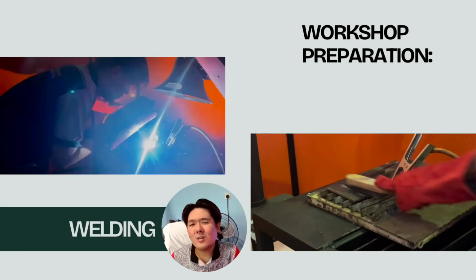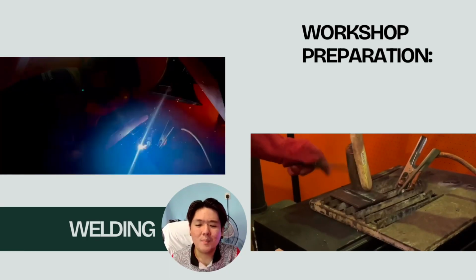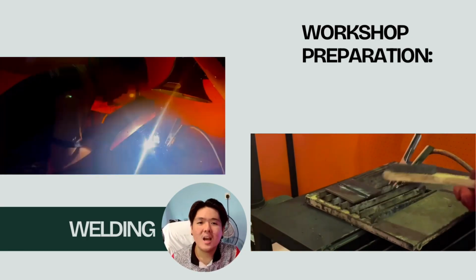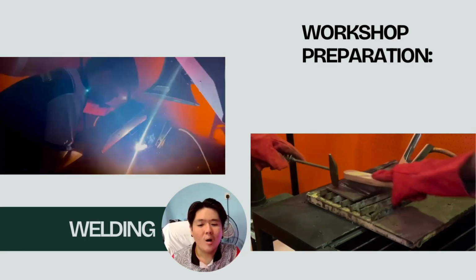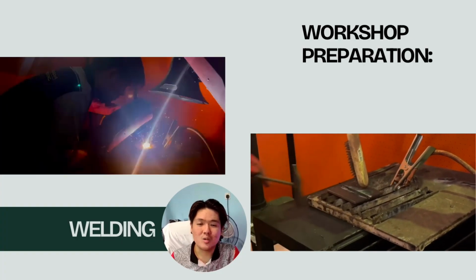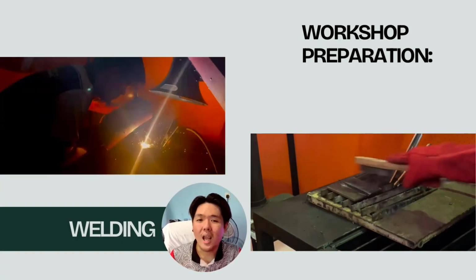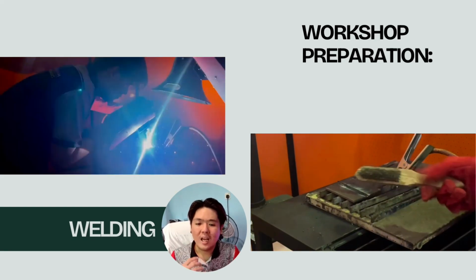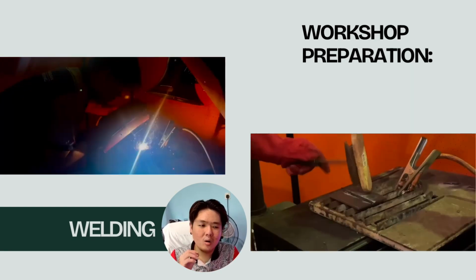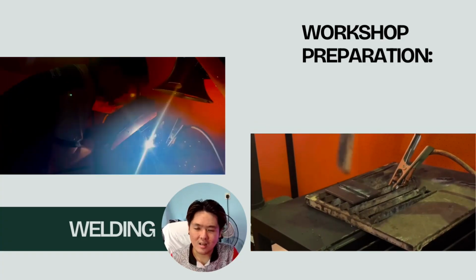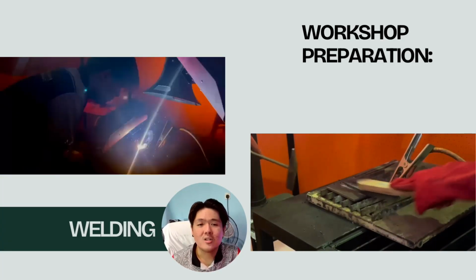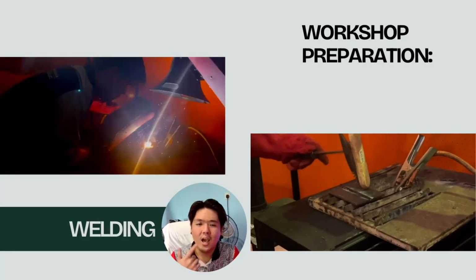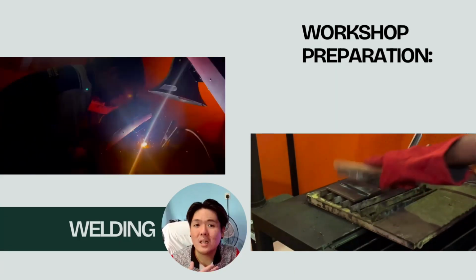Good welding quality depends on proper surface and joint preparation, using the correct settings, which we set at around 80 ampere of current, and using the multi-pass welding technique for thick materials or for high joint strength. These steps ensure a strong, safe, and reliable welded joint.